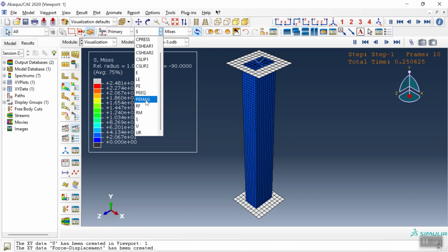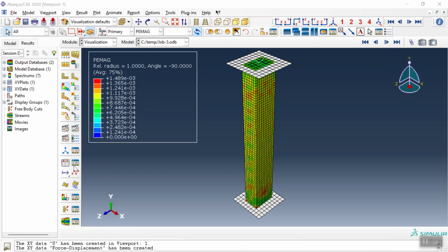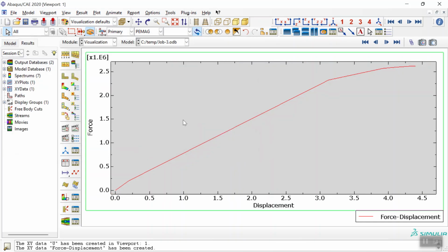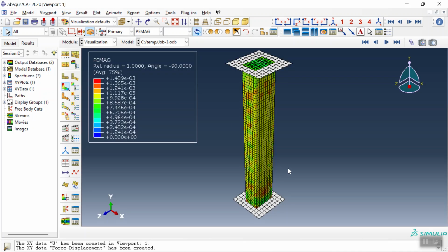Okay, this is the model, and we also have the force-displacement diagram. For this example, we read 2.5 meganewton as the maximum for this displacement for this model, but we can keep it going to obtain the full failure model. It would happen at around 6 millimeters.